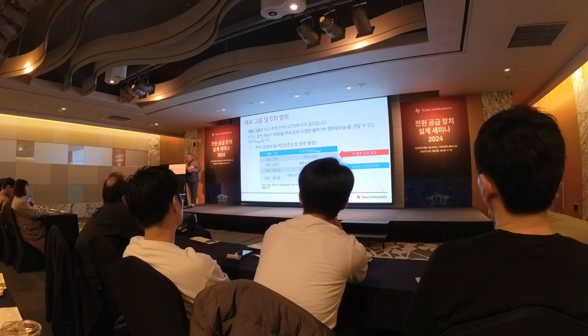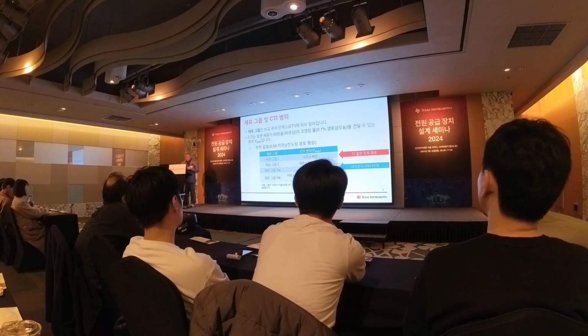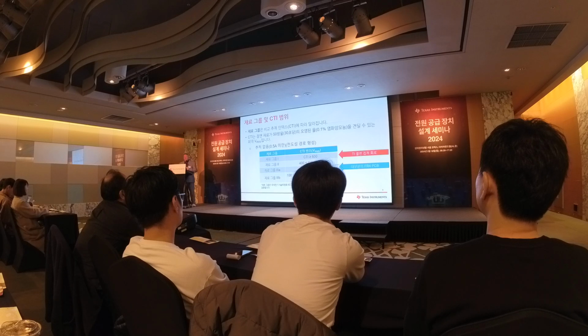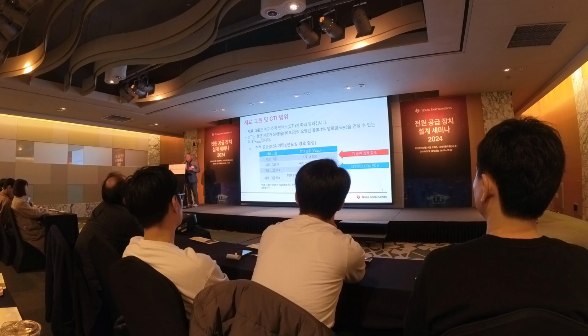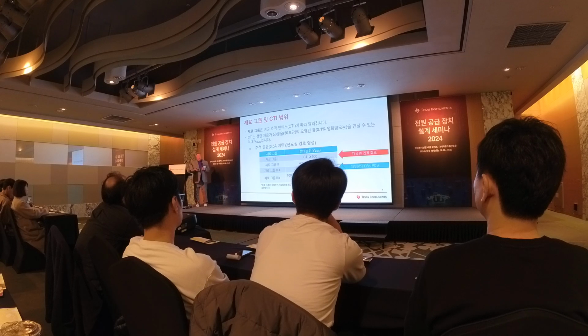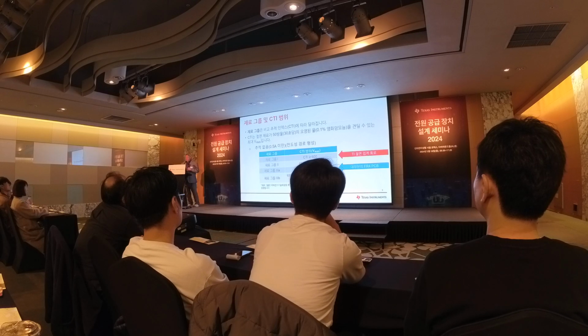Okay, let's first talk about material groups. And when we talk about material groups, we're going to use something that's called the Comparative Tracking Index, or CTI. So when I say CTI, what does that mean? Basically, it has to do with the maximum voltage at which an insulation material can withstand 50 drops of contaminated liquid, and this contaminated liquid is a solution of 0.1% ammonium chloride.